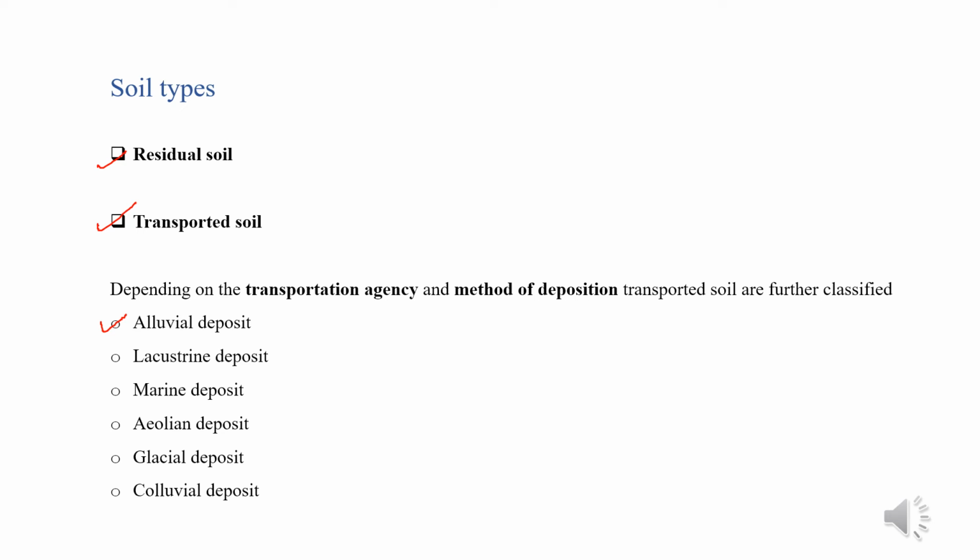Basically we can see these alluvial soils near floodplains. Like in India, a large part of this soil remains in the Indo-Gangetic plains or the Brahmaputra floodplains, or some parts of northern India lying north of the Vindhya Satpura range. These soils basically comprise alternating layers of sand, silt and clay.